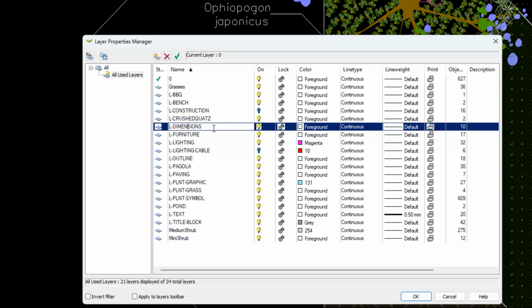You notice that in this case, the designer has followed the conventions that most of us use in the landscape area, because if you're dealing with passing this drawing to others, you want your layers indicated very easily, and we've prefixed the layer name with L-, and that's an international standard for layering conventions. It certainly helps when you're moving drawings around from architect to designer and so on.